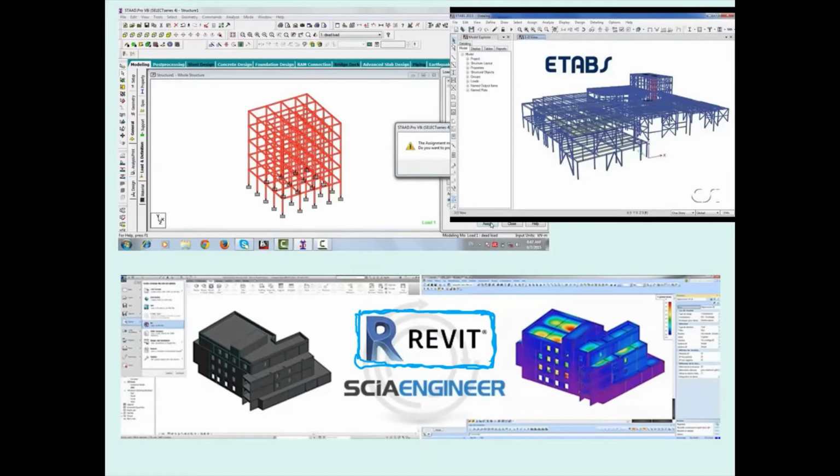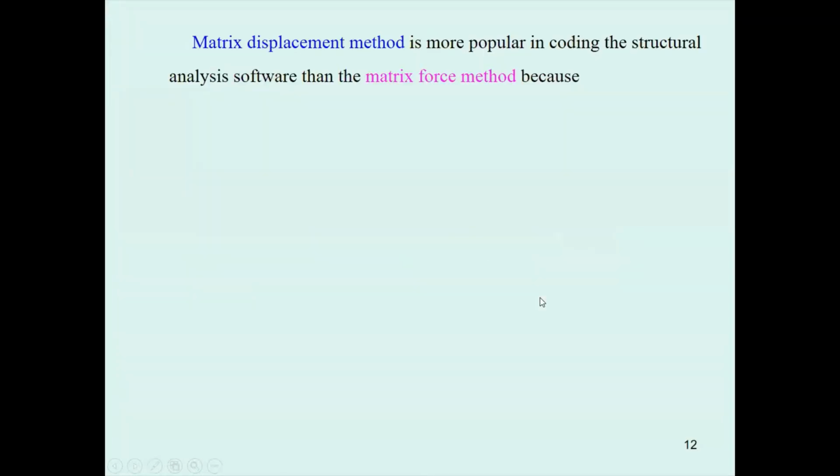Then when they use the computer, that engineering sense is used to recheck the structural response the computer generates. They worry because if you put junk or misinformation into the computer, it will generate junk out, garbage in, garbage out. Only engineering sense can detect it. It must follow sense first before you accept the result of the calculation.